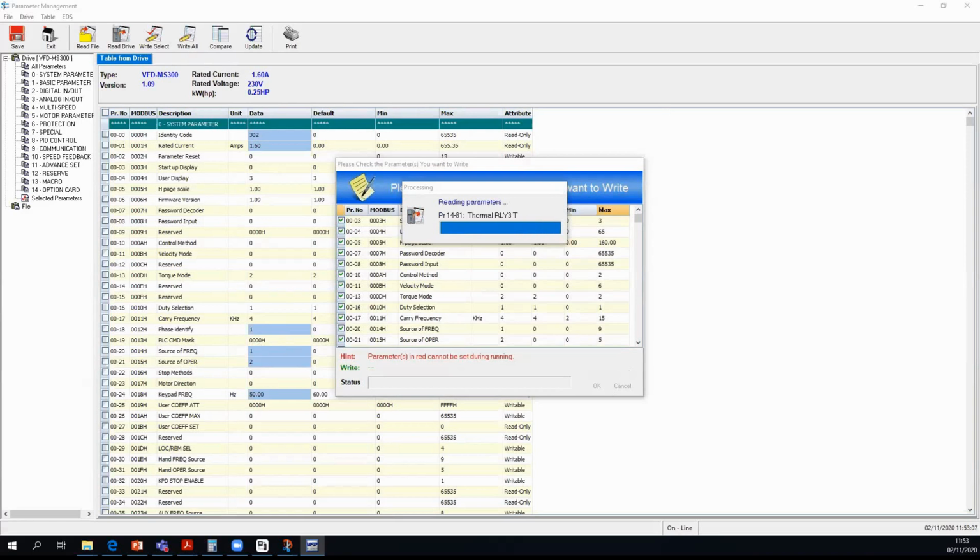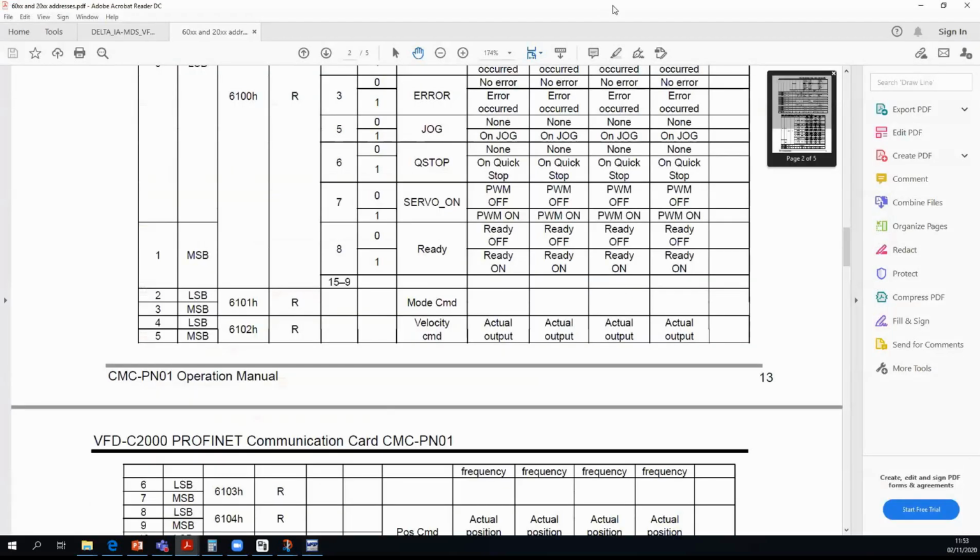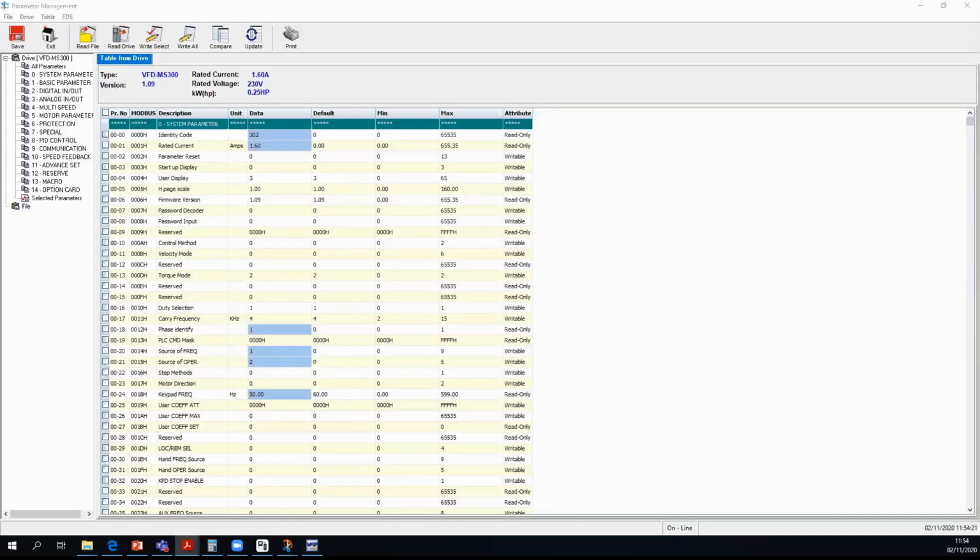Oh, in the meantime, I see there is another question. So in point-to-point mode, can you use parameter 415 and 416 to set a command from the drive only? Yes, that is possible. You can have a range of different combinations for the digital inputs, and then you can just send the drive to a position based on those parameters. In fact, we have a quick guide on that. I will open it. Let me see.